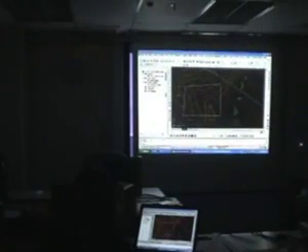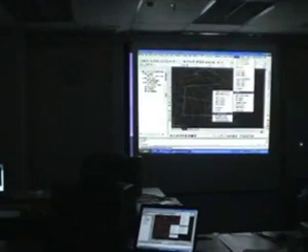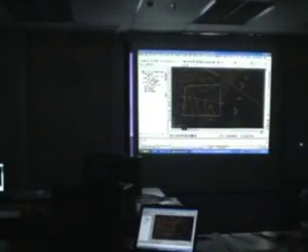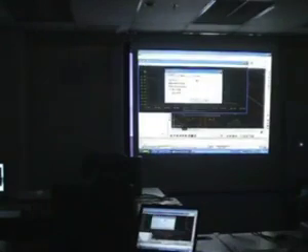In fact, if you want to check the sections, we'll use the quick section tool. I'm just going to select this. You can see now you can see more than one profile. You can actually see up to a maximum of 8. If I go to view properties, you can see up to 8 different surfaces in the same profile view.